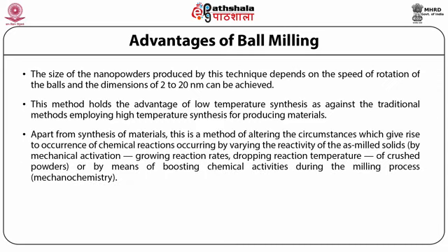materials. Apart from synthesis of materials, this is a method of altering the circumstances which give rise to the occurrence of chemical reactions by varying the reactivity of the as-milled solids by mechanical activation, growing reaction rates, dropping reaction temperature of crushed powders, or by means of boosting chemical activities during the milling process, which is mechanochemistry.